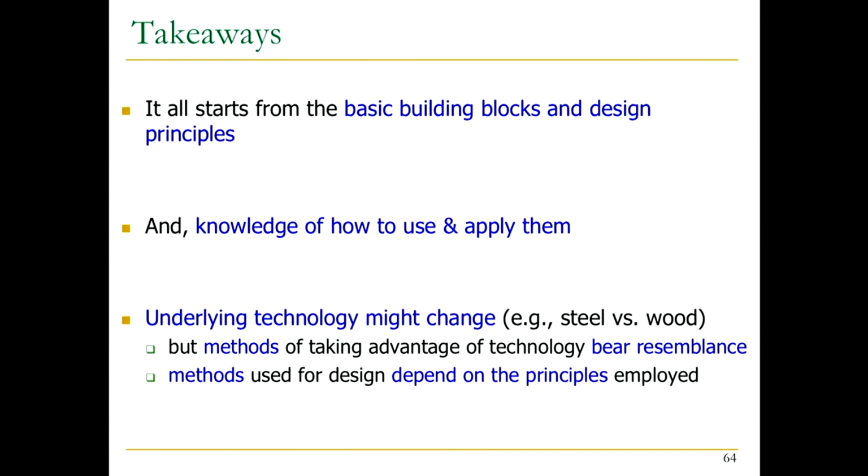It's a two-dimensional array in this case, not the one-dimensional cells that I mentioned. You bring the inputs from here, X inputs, and then Y inputs here, and the data flows. You do the calculations, and you pull the data out after that. So this architecture is real now because it is based on a very solid principle. The principle is saving memory bandwidth,